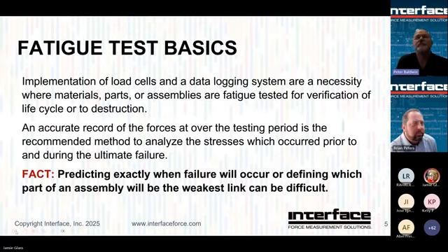Right? So as part of those basics, implementation of load cells in a data logging system is a necessity where materials, parts, and assemblies are fatigue tested for verification of life cycle all the way to destruction. You want to be able to have an accurate record of those forces over that testing period to analyze the stresses which occurred prior to and during the ultimate failure. And keep in mind, predicting exactly when that failure occurs or defining which part of that assembly will be the weakest link can often be very difficult.